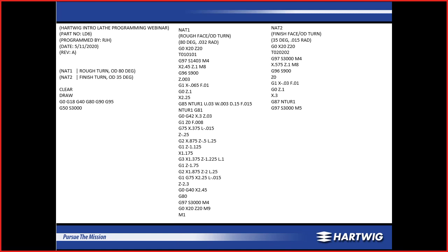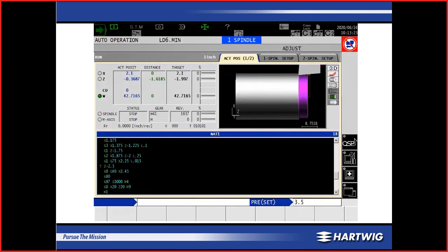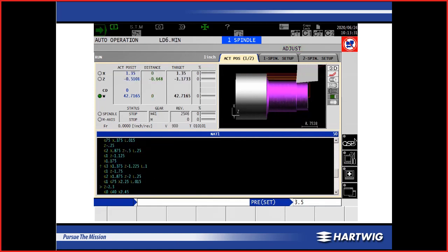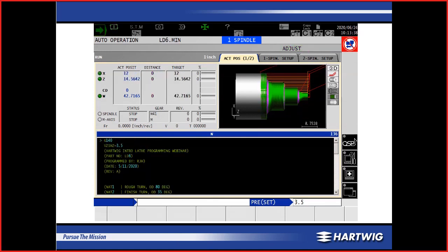We're going to turn off the spindle with M5, rapid to the limits of the machine and shut off coolant, and end the program. Now that we've walked through an example of this program, let's see it run in a simulation video. So we see our roughing cycle running. Our finishing tool comes in, faces off the part, finishes the shape, and our program ends.